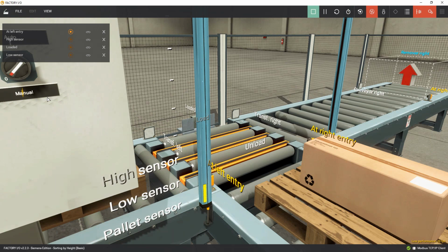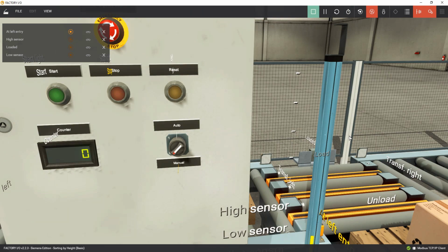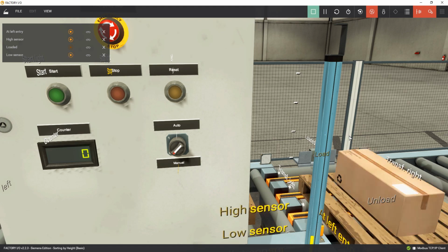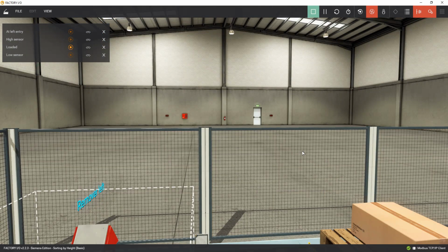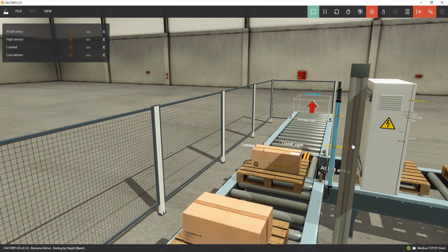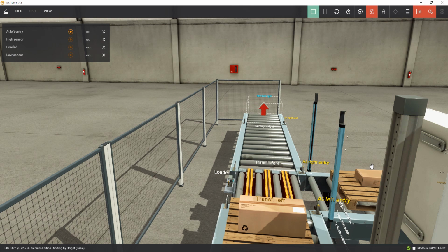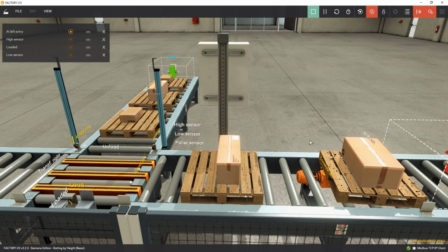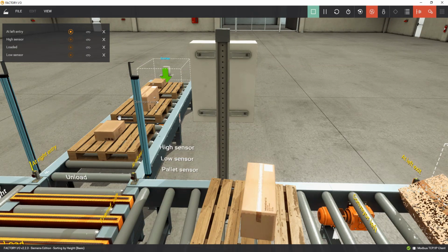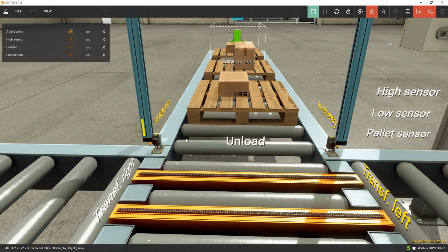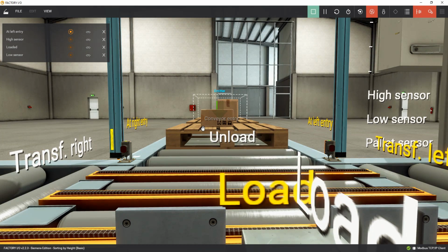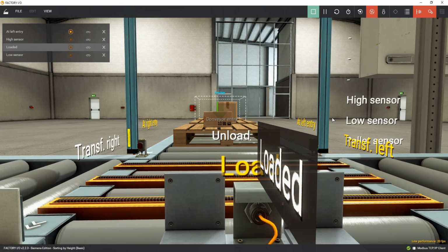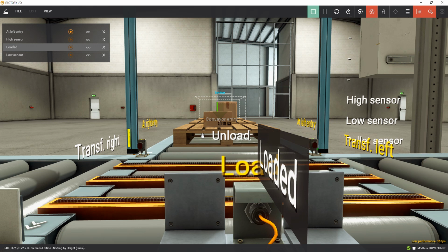Let me prove it to you. The chain won't stop at the current moment. So start. When we reach there, I3, the conveyor belt moves lovely, and the transfer chain, see now the transfer chain doesn't stop running even when we pass the stage. The transfer chain doesn't stop, and it has to stop. So the sensor there is the one that must stop the transfer chain and must start the conveyor belt there. Right? Let's do that code.